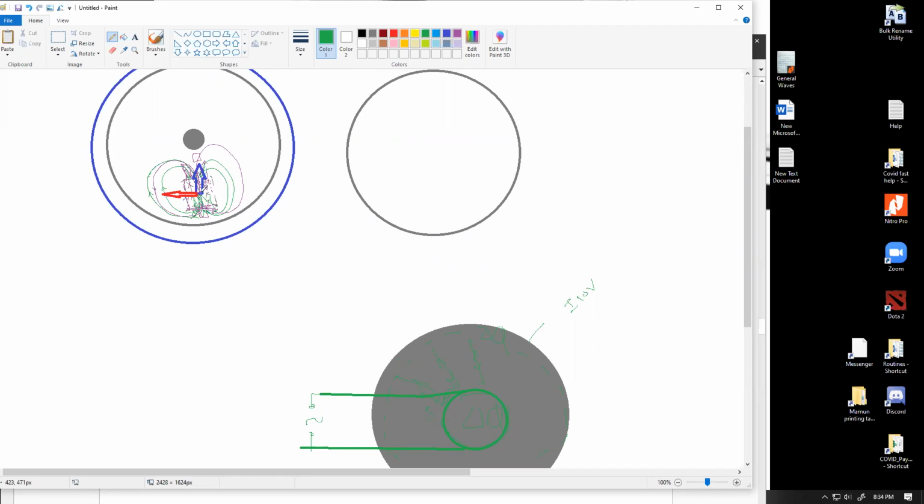In the earlier case, we were applying a fixed magnetic field, a fixed strength of magnetic field. For example, this magnetic field was introduced by some permanent magnet, or by a DC solenoid of fixed current value, and the disk was rotating. That was producing the eddy current because different segments of the metal piece were affected by different values of magnetic flux linkage. Some places there was magnetic flux linkage, some places there was no magnetic flux linkage. And that was the case for that one. So the variation over there was produced by the physical movement of the disk. The variation in this case is being produced by the variability of the supply, or the magnetic flux itself is variable over here. The disk is not moving at all.